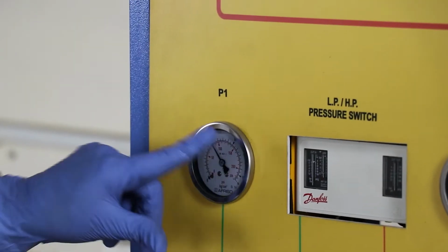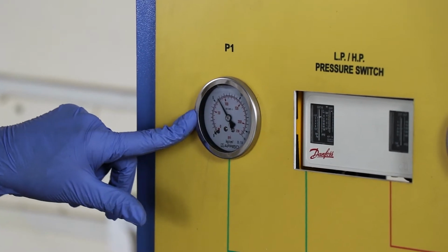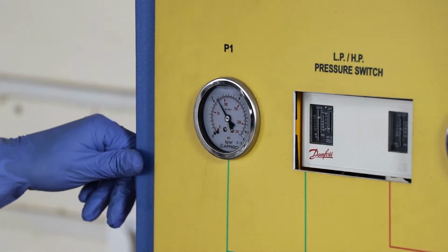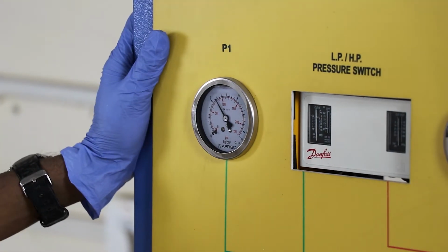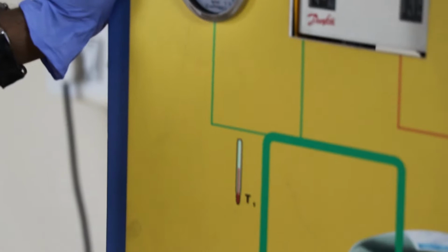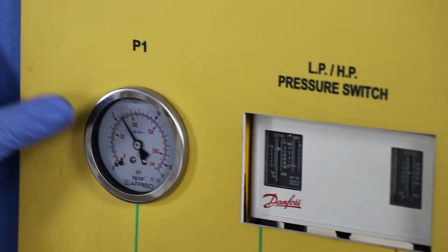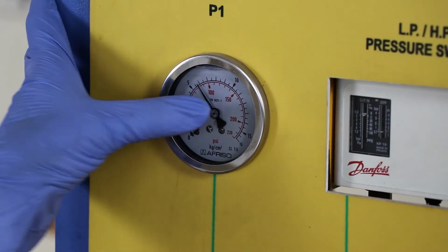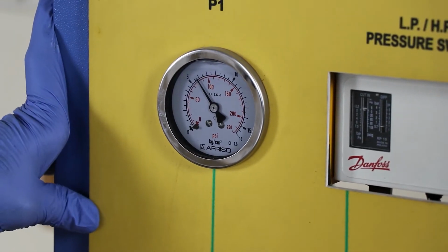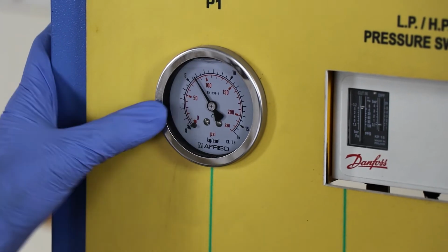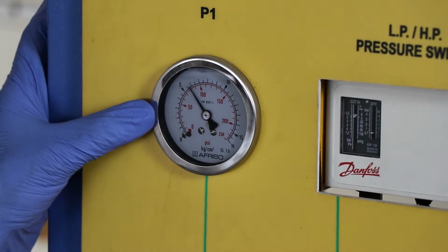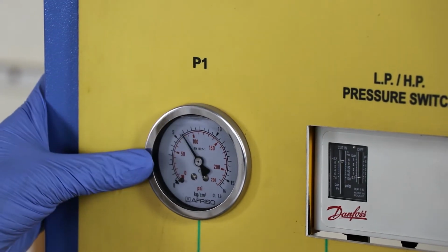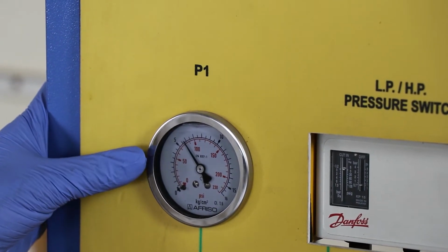One red one is inside a scale which is in psi, and the black one is in kilogram force per centimeter square. Now both these units are not in use because we are using SI units, so they are not in use. Neither the kilogram force per centimeter square nor the pounds per square inch is used. So we have to convert this reading into the bar unit or SI unit or pressure unit or Newton per meter square unit, something like that here.